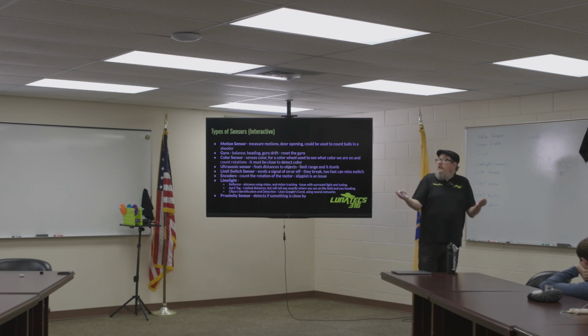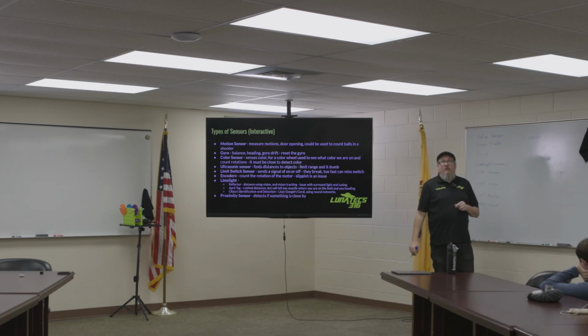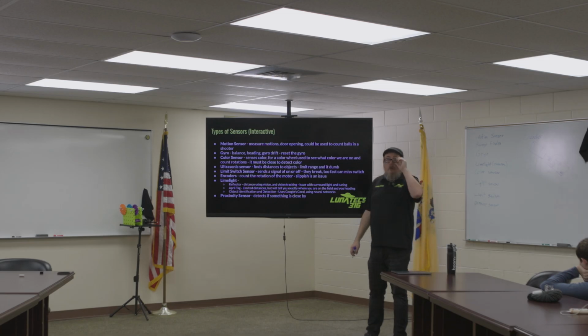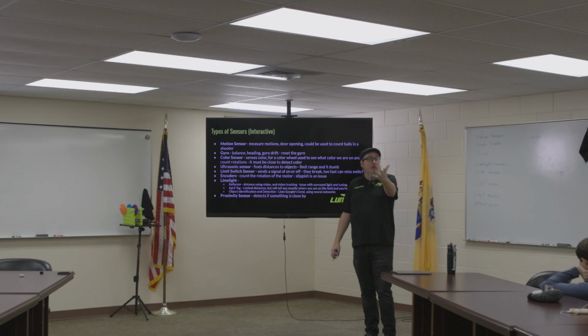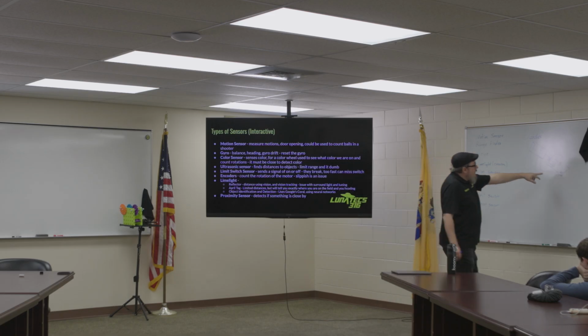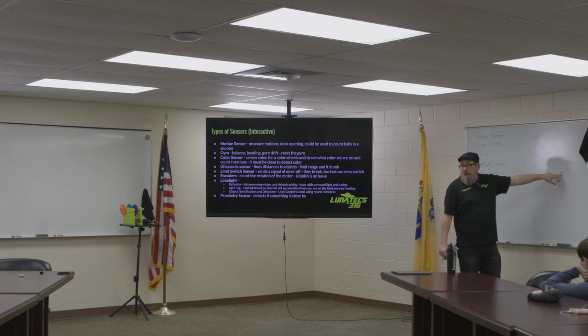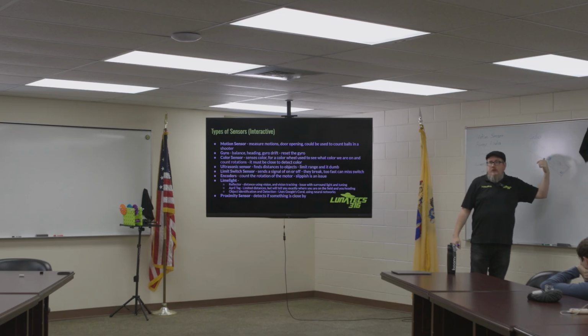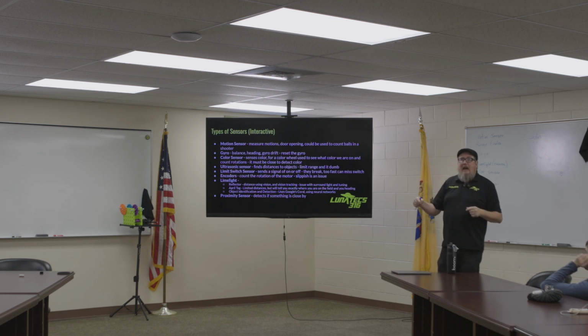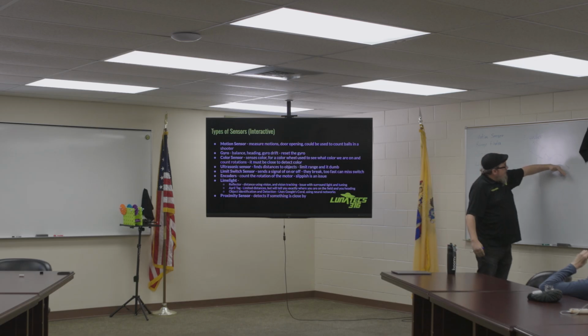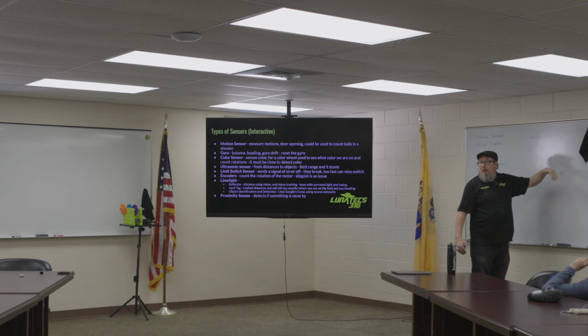So we needed some way to stop it. Go ahead, Mark. When it gets close enough, it would stop. It didn't quite stop the motors. We did a little sequence, but essentially it was there to stop the motors. When this rangefinder saw something within 2 inches of it, the opening was, I think, 4 inches wide, it ran the motors backwards and then stopped them. It ran backwards for a quarter second, very quick. If you saw it shoot out a little bit, it would suck it back in and then stop.